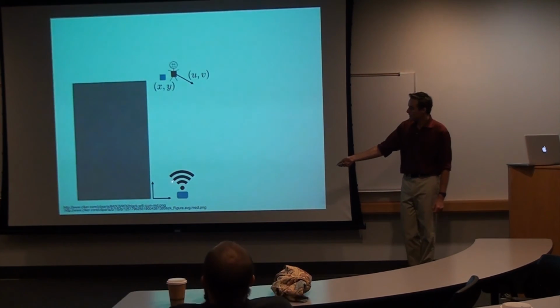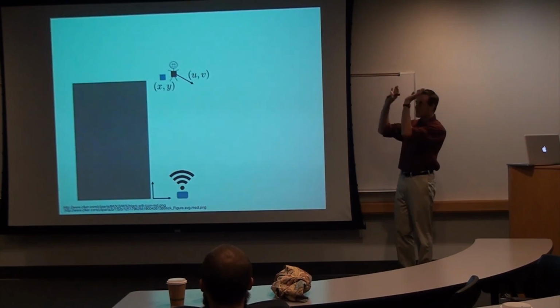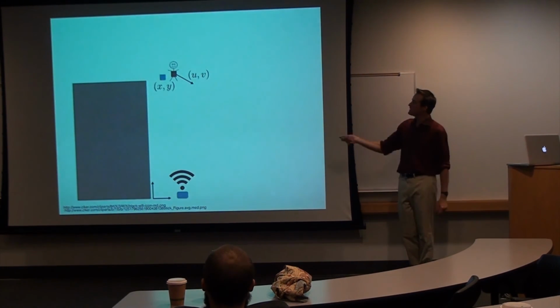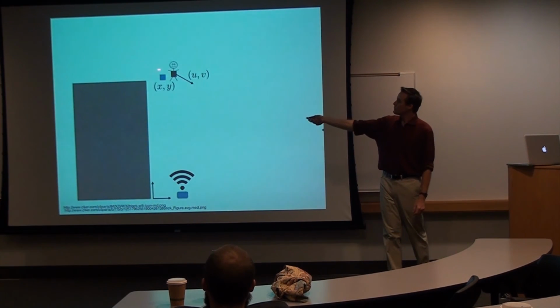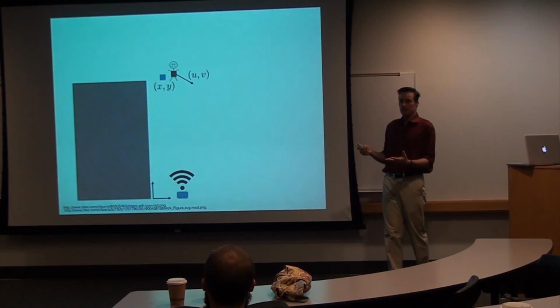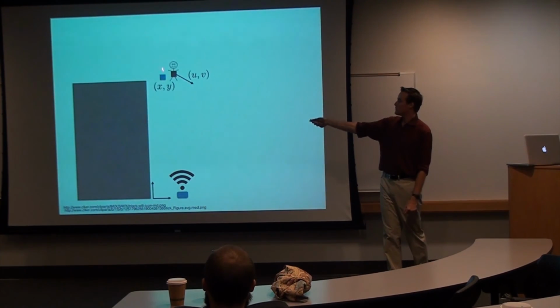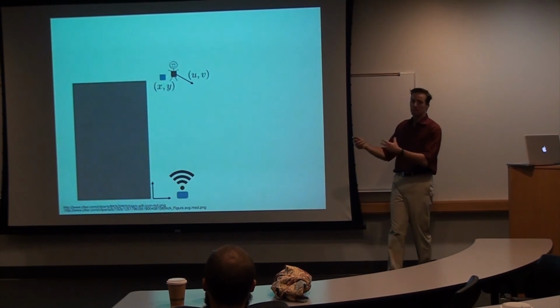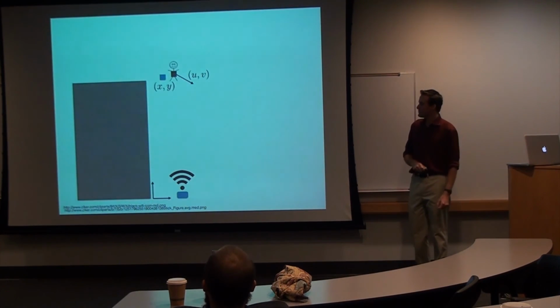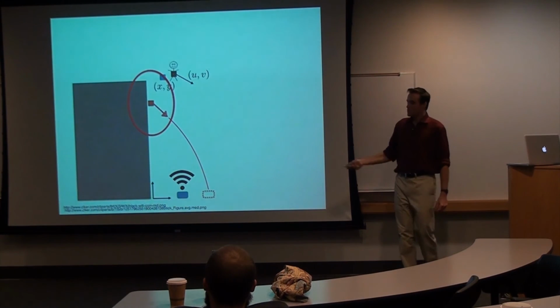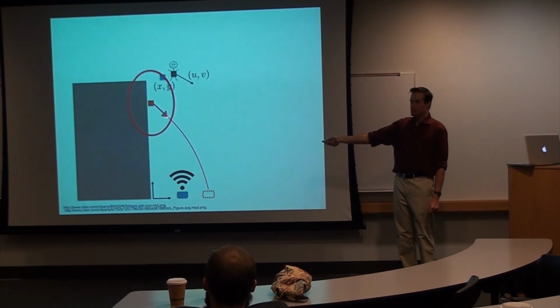The cushion, we're saying, can use some sort of LiDAR scanning in order to read his position, which is this blue dot. But it doesn't measure his velocity. It just gets his position. And you can probably imagine there's a difference in the noise it measures. It can probably tell this direction pretty well, but depth maybe not so well, so you could have different covariances in those two directions. Based on the sequence of measurements it gets as the guy is falling through the air, the Kalman filter will produce an estimate of what his position is and what his velocity is.